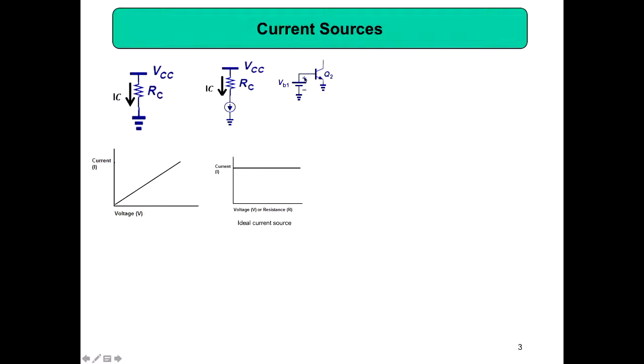So you can connect a fixed voltage VB, because if you connect a fixed voltage VB, then your current will be constant. Even for MOS, you can use the same, because when you draw the small signal model, this is a constant DC voltage, so it will be grounded, and then this part is anyway grounded, and then gmVB, that is a current source.